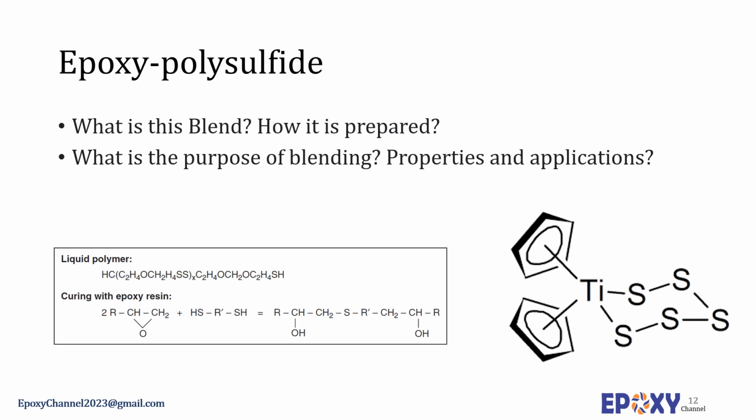For adhesive systems, the liquid epoxy resins most widely used with LP3 polymers are liquid unmodified and diluent modified bisphenol A resins and liquid blends of bisphenol A and bisphenol F resins. Solid bisphenol A, multifunctional and aliphatic diepoxy resins have also been used with these types of resin. Ratios of liquid polysulfide polymer to epoxy are in the range of 1:2 or 2:1. An increase in elongation and impact strain is the result of increased amounts of the liquid polysulfide polymer.